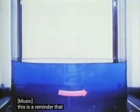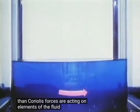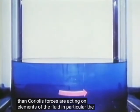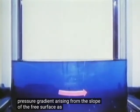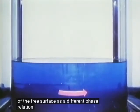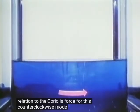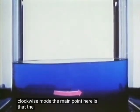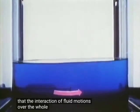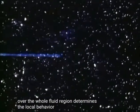This is a reminder that forces other than Coriolis forces are acting on elements of the fluid. In particular, the pressure gradient arising from the slope of the free surface has a different phase relation to the Coriolis force for this counterclockwise mode than for the clockwise mode. The main point here is that the interaction of fluid motions over the whole fluid region determines the local behavior.